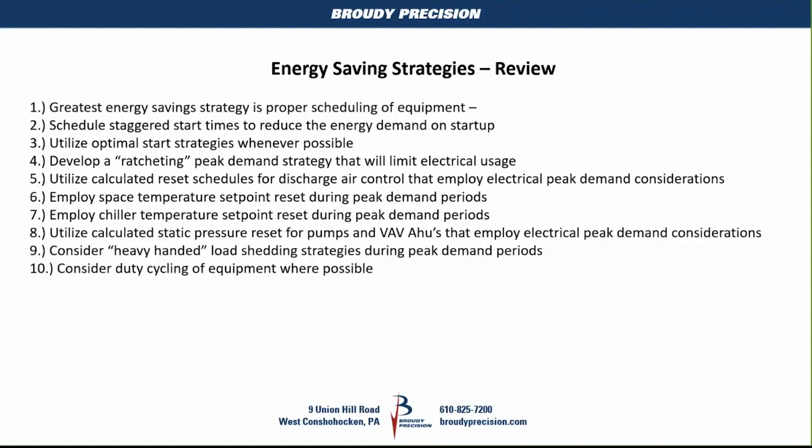If I exceed 10,000, it's going to change my rate and I'm going to go up in utility usage. Just using round numbers here, my absolute shutdown is 10,000 kW. So the goal is to keep it below 10,000 for any given time interval, whether that's our 15-minute or 30-minute sliding demand. We're trying to keep our counted kWs, our instantaneous value, below that high limit, and we do whatever we can by reducing instantaneous usage of energy to keep that number down. That's what I mean when I say ratcheting.